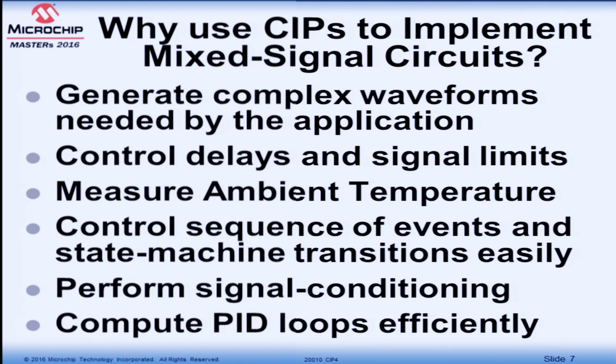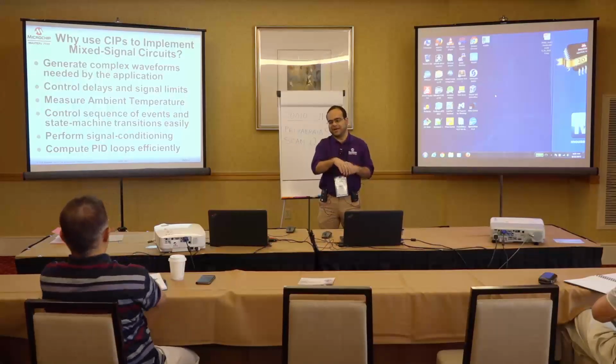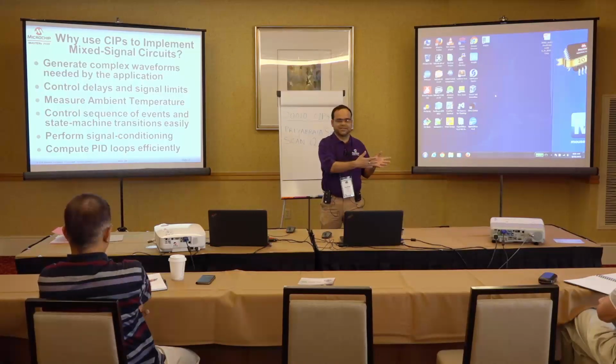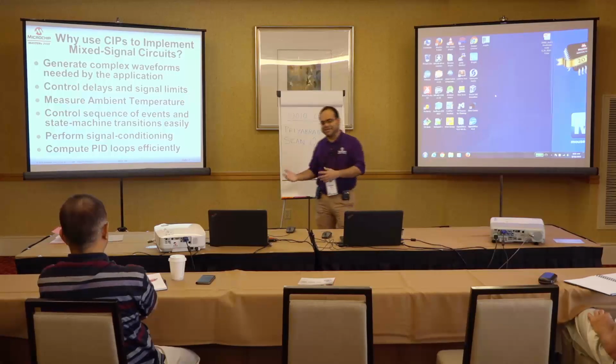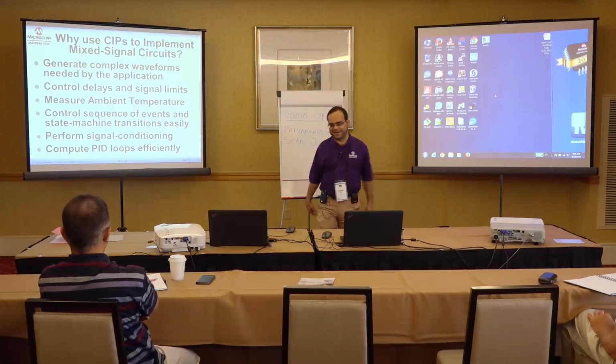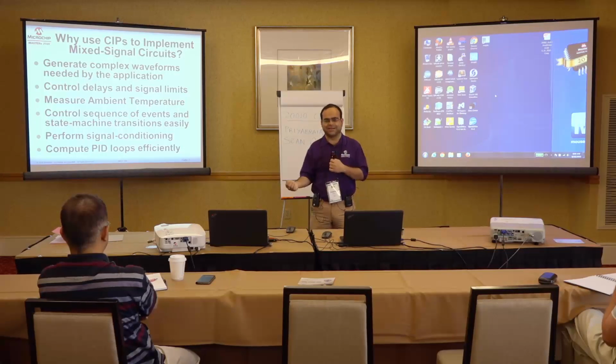So, we are dealing with various analog signals. In many cases they could go off limit and exceed its upper threshold or fall too low below its lower threshold, and we have to be able to detect such conditions or scenarios very quickly and respond to them without having the CPU get interrupted and perform some corrective action. So, these peripheral modules should be able to work in conjunction with each other to detect such abnormalities and take corrective action, maybe shut down some machinery and so on.